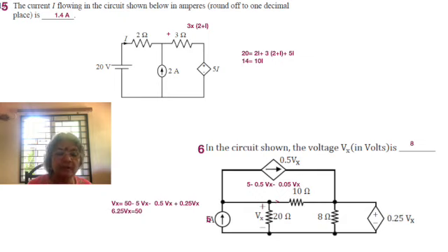Once we have that, we can set up the voltage equation. Don't look at the 5 ampere source for giving you a voltage, but you know that there's Vx across 20 ohms. So Vx can be equated to all the voltages across it, which has two constituents. One is 0.25 Vx at the other end, and we also have in the same direction 5 minus 0.5 Vx minus 0.05 Vx, into 10. That is the voltage drop across the 10 ohm resistor.